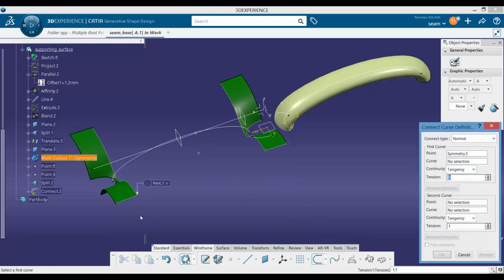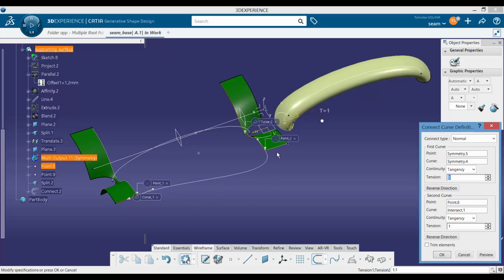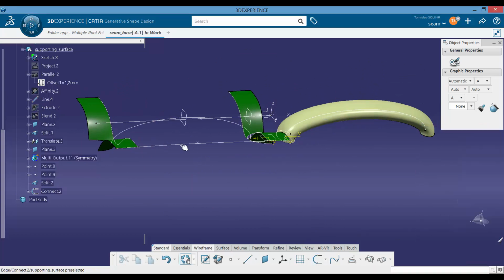So we'll select the point, we'll select the curve, we'll select the other direction only once, then we'll select the other curve, other support, and we will additionally project this on our desired surface. And the surface was that extrude that we created before, so let's project it.